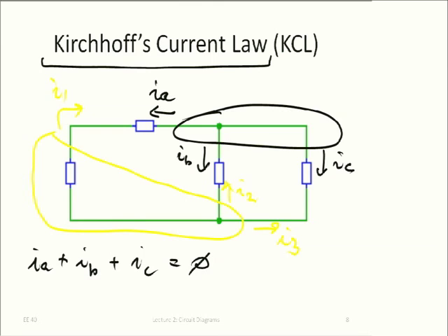Likewise, in Kirchhoff's current law, I can sum up all the currents that leave a node, and the sum must be 0. I can sum up all the currents that enter a node, and the sum must be 0. Your choice. I always use the currents that leave a node, but that's perhaps only because over the years some of us get habits. It really doesn't matter. Right? And of course, you also can make combinations. You can have some that enter, some that leave, and if you sum it up just right, then you get the right equation. Anyways, it's a little bit more tricky. All right, so that's Kirchhoff's current law. Very, very simple. Works like water in pipes, and it's terribly important. We'll use this all the time.